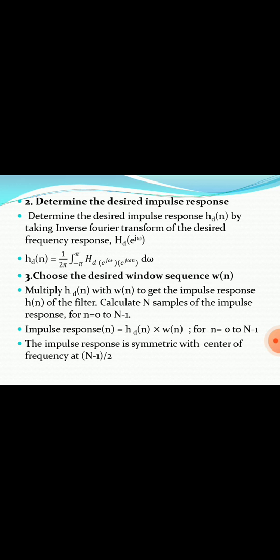Next, determine the desired impulse response. The impulse response is calculated from the desired frequency response by applying the inverse Fourier transform.